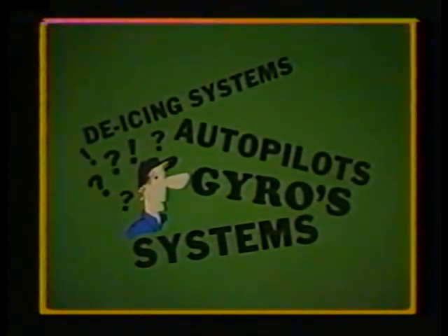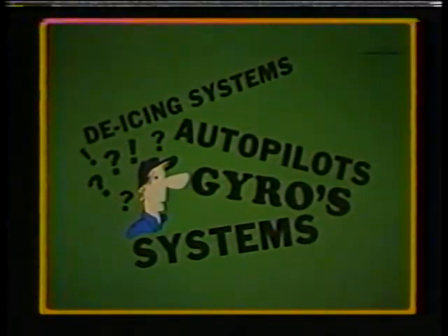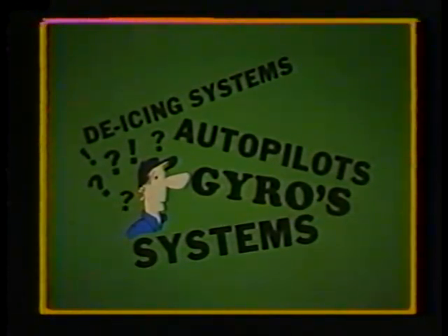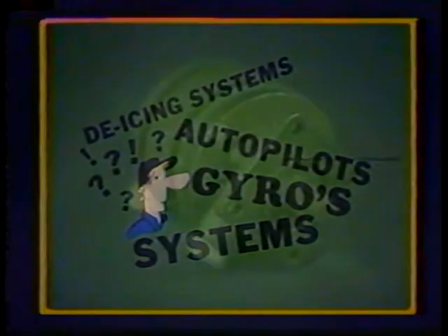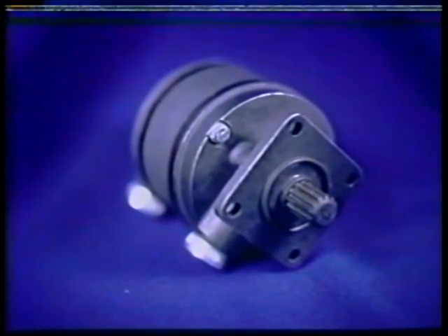As the state-of-the-art in autopilots, de-icing equipment, and gyroscopic instruments advanced, an absolutely clean, oil-free air source was needed. In order to accomplish this with an oil-lubricated pump, additional oil-air separation devices were necessary, increasing the overall system weight. To avoid this problem and meet the demand for clean oil-free air, a new type of pneumatic pump, a self-lubricating dry air pump, was developed and is currently available from a number of component manufacturers.